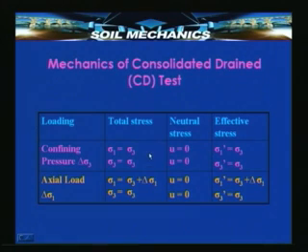Then whatever stress we apply immediately becomes a total stress, and the total stress values will therefore be lateral pressure sigma 3 equal to the applied pressure sigma 3. The vertical pressure is also equal to the applied pressure sigma 3 because the sample is surrounded by water on all sides.